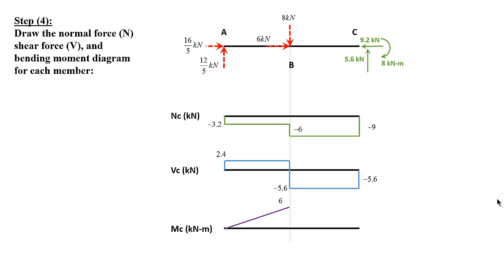Now I know that the moment diagram should go down, because remember, this is the maximum positive, because at this point the shear force crosses the x-axis. But to what negative value should I go? If I look up, I have a negative moment acting at point C of a value of 8 kilonewton meters, which is a negative value. So the graph should go all the way to this value, -8, and closes.